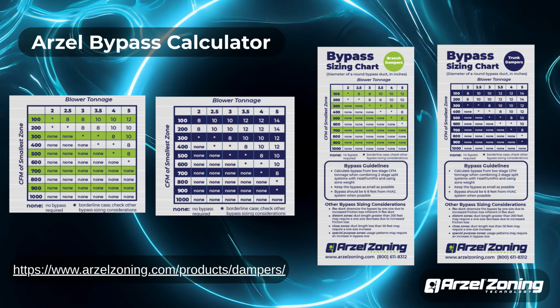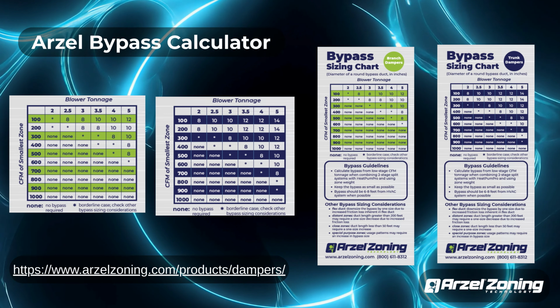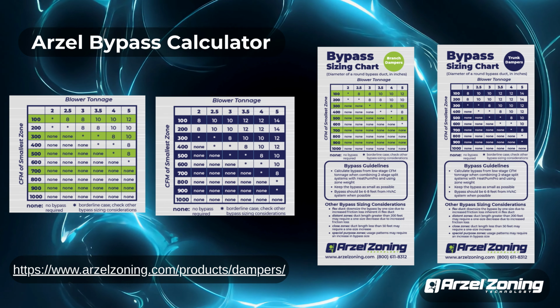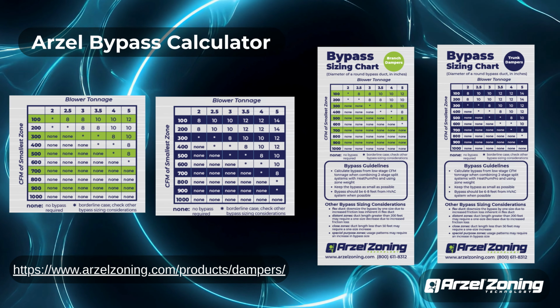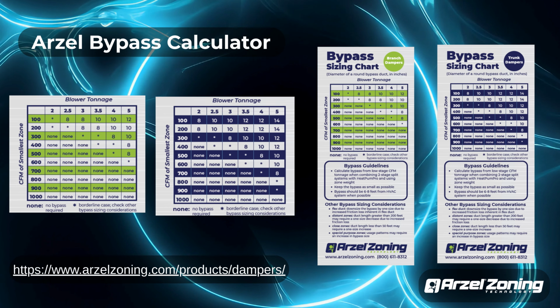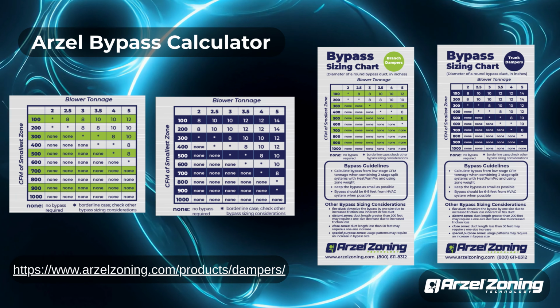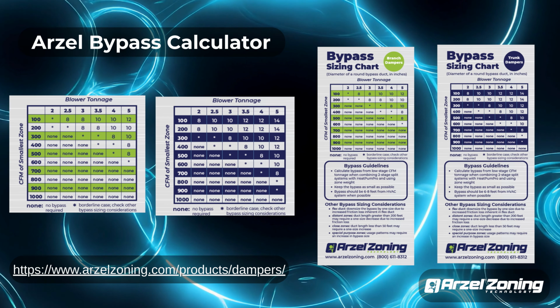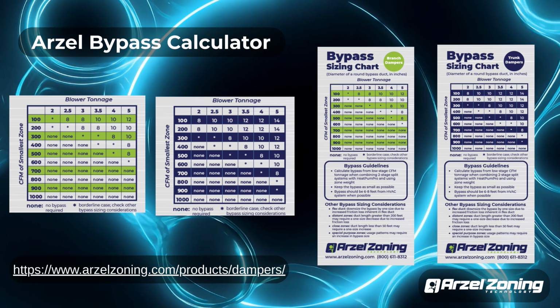I don't have very much length or frictional loss to eat up velocities or air noise. I might have to go up a size in a bypass. Or if I'm on the borderline and I'm not sure if I need one or not, I might want to plan on figuring in a bypass because my smallest zone's right above the equipment. Special purpose zone, that's another factor you have to take into consideration.